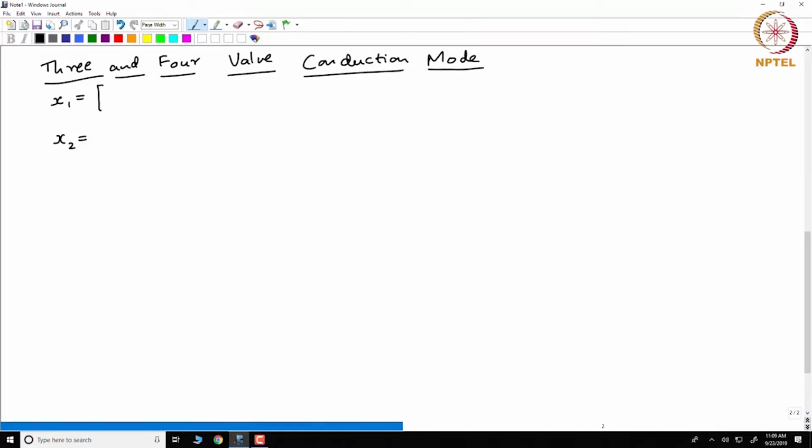See, ID is something which is given to us. So the current source is something which is known. So, one of the currents is ID, which is a loop current which is known. So, there are only 2 loops. Okay, so I can say that x1 is having 2 elements. So, I also know that the second element or the last element of x1 is I6.